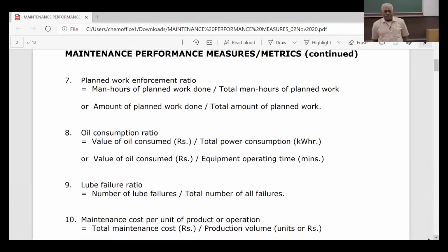And please also understand, there may be instruments involving electronic components which are known to fail suddenly. In the case of mechanical parts and components, there is wear and tear, and if you're quite experienced, you will have a good idea of the wear and tear, and the anticipation of failure will be quite good. You'll be quite accurate in anticipating failure, because you'll be able to judge the wear and tear. For example, noise is a good indicator of some wear and tear. You'll get rattling noise in equipment and so on.